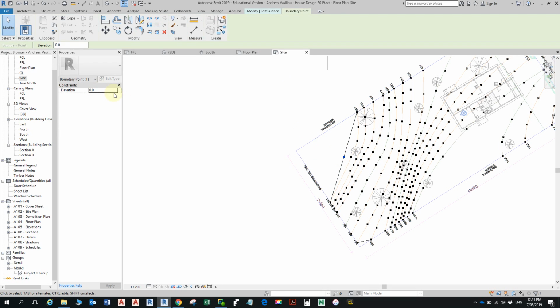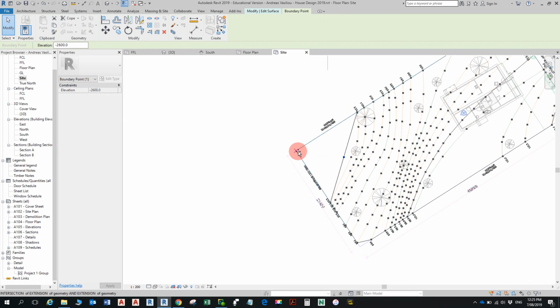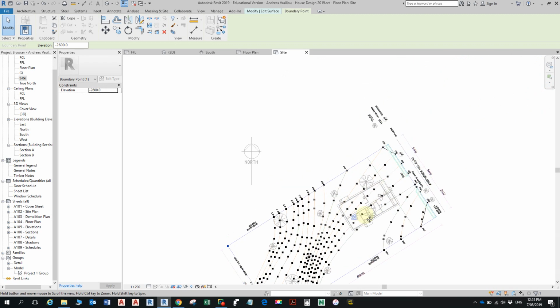So it's really sitting 2.6 meters above where I want it to be. So I'm going to come here now and Control V and paste that number in there, and that takes it down. All right, so it's on the same level as those. And escape one more time. And now I can click on this point and drag it over here. All right, so in theory, that's closed that gap there.